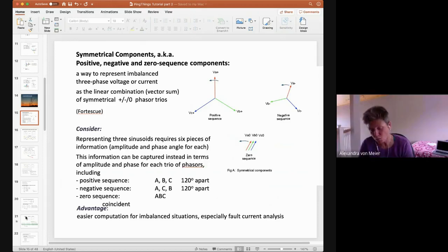There are ways to improve upon this information loss by defining phasors in a way that describes sort of a best fit to a variable frequency, and also reports a goodness of fit measure. So you can still just report one or two frames per cycle, but with each frame, if you do the phasor computation a little differently, you can, first of all, maybe have a little more intuitive fidelity of what happens when there are step changes.